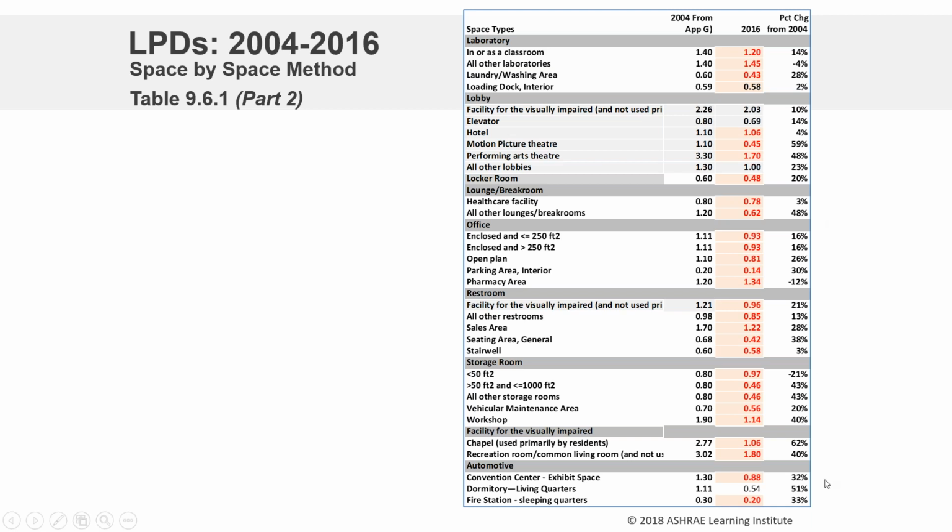These also get updated based on the technology that's available. So 2016 was a mixture of fluorescent and LED when we were designing these lighting power numbers. 2019 goes to 100% LED. So the numbers generally come down a little bit further for 2019. You will note that some of them have gone up, and part of that is because we rebuilt some of the models that were used to calculate the lighting power allowances, and some of them had to be updated just because they were old and had not been updated.